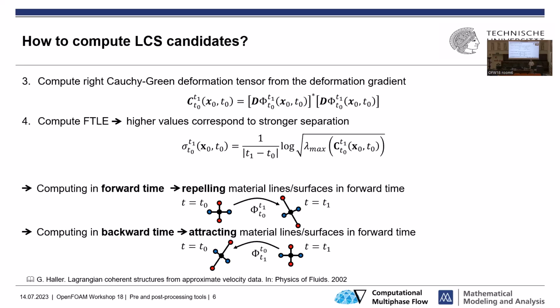And especially interesting, this tensor gives you information on how your continuum or your fluid is deforming over time. The eigenvalues and eigenvectors give you directions and values of how it deforms. The higher values of the eigenvalues of the right Cauchy-Green tensor correspond to more separation of particles, or more divergence of the flow. Not really the divergence you normally see, but the separation of the particles.